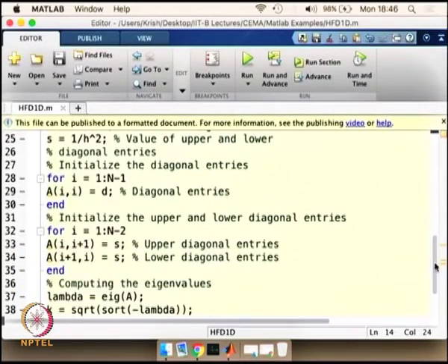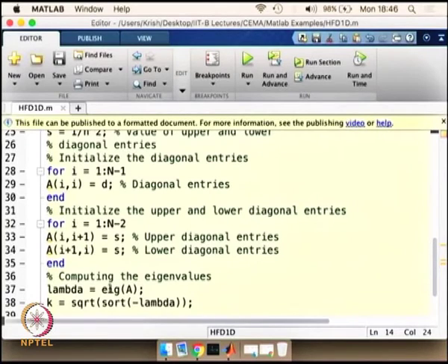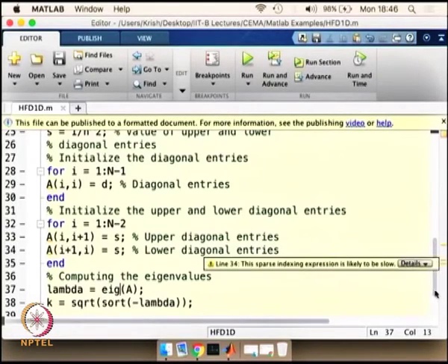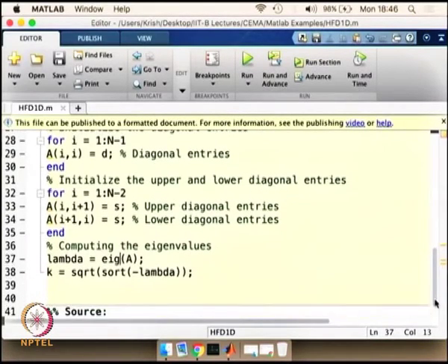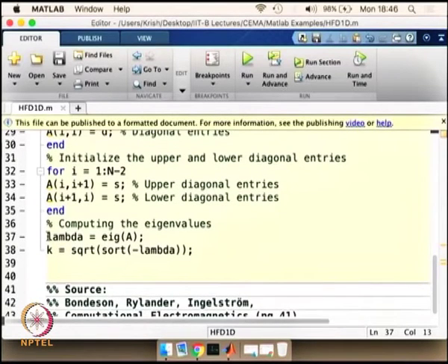What we are using is a simple MATLAB function called Eig, which works very well in a one dimensional case, and also in a two dimensional case it might be useful, but once you go into a three dimensional problem it will not be useful. There we are going to use a different function which is called Eigs with gs at the end, but for this one dimensional problem we can still use Eig as inbuilt function, and we can compute the value of the lambda using the eigenvalue of the matrix what we have here.